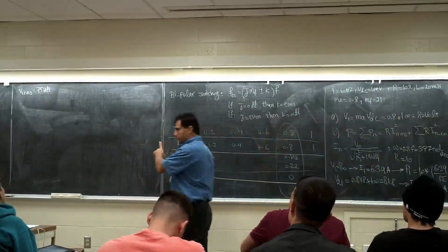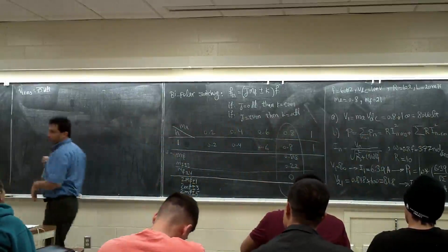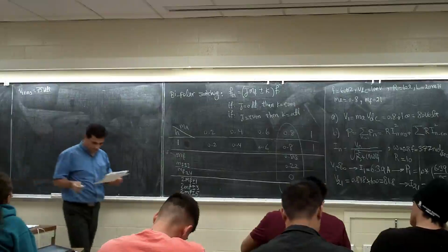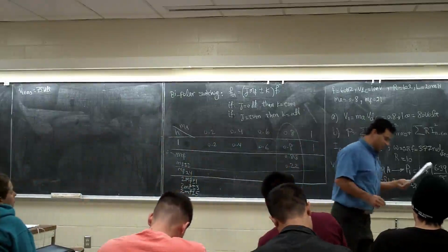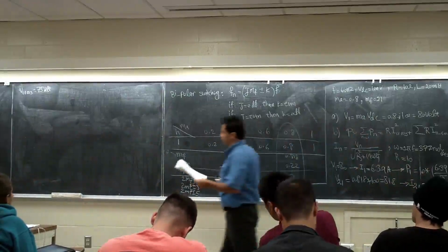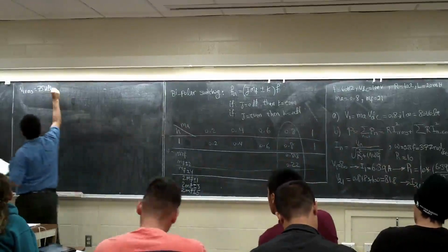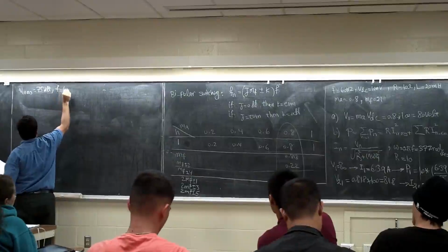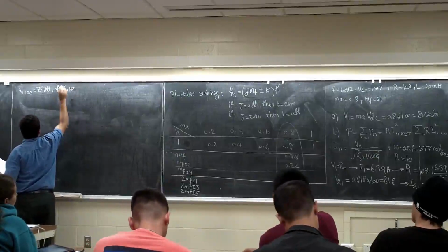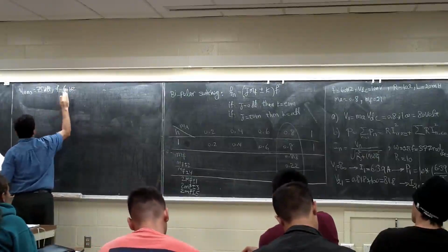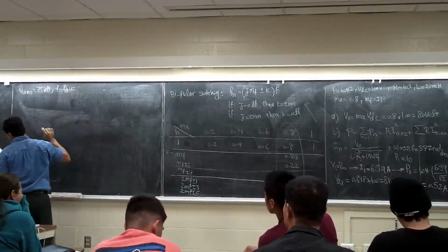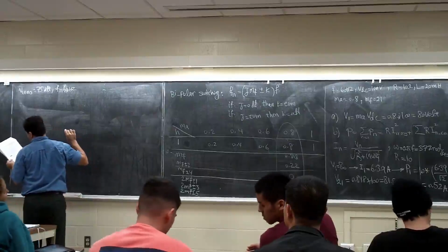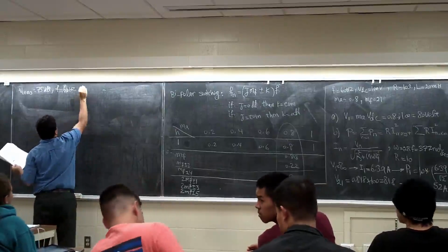You said we want to design a PWM inverter that has 75 volt out, RMS. 75 volt RMS at 60 hertz is given to us. It says it's a 60 hertz inverter, and the output is from a 150 volt DC source.